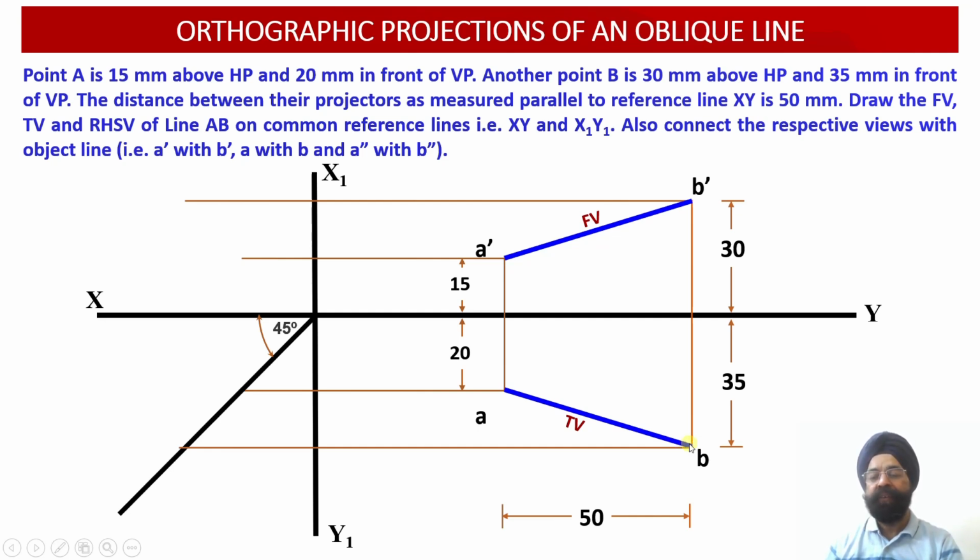So for that, we are going to draw a horizontal construction line originating from the point B such that this horizontal projection line will be extended up to the transfer line which we had already drawn earlier. Once this horizontal construction line intersects with this transfer line over here, now from point A coordinate and from point B coordinate over here which is available onto the transfer line